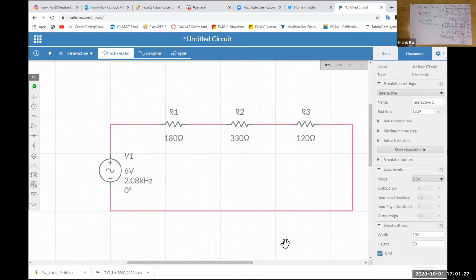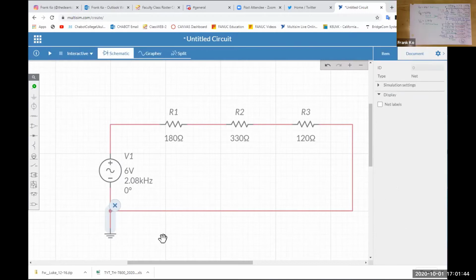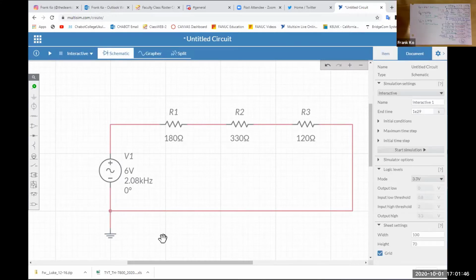Now I have a really nice drawn circuit so far. And one more thing I do need to add is my ground. So come over here, select this, and I do want ground. So select ground, and I will go ahead and place a ground right there. And my spool of wire, I will make a connection. I have a node. Looks pretty good so far, yes?